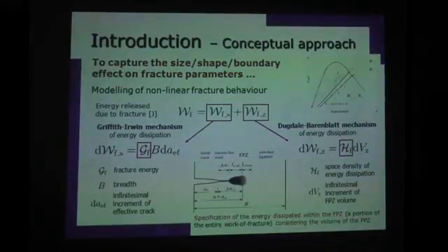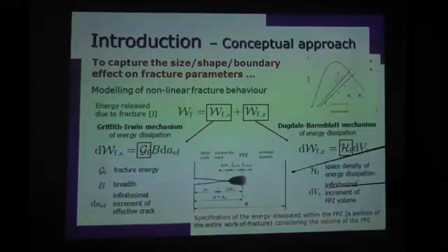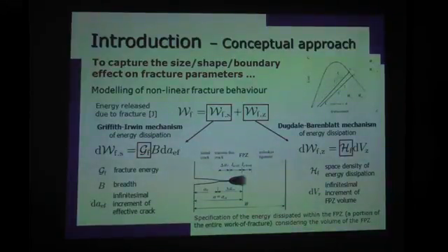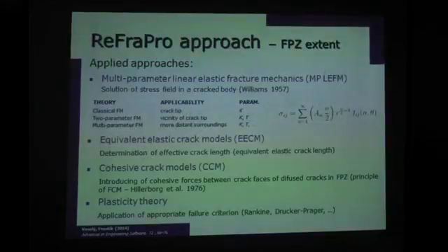So the portion which is dissipated for the crack propagation is linked to the classical fracture mechanics approach, and the energy dissipated within the volume of the process zone should be specified by the parameters of that zone.